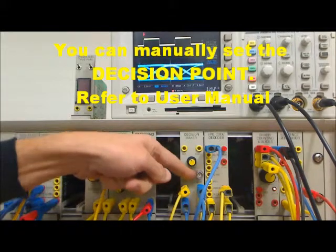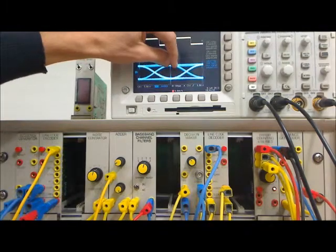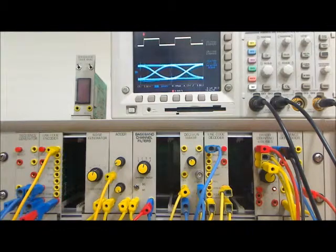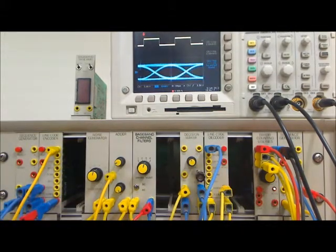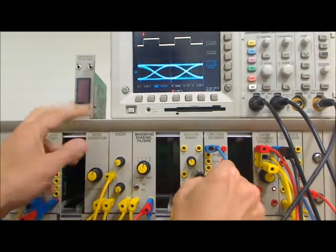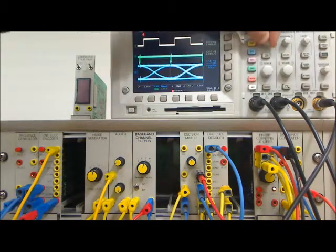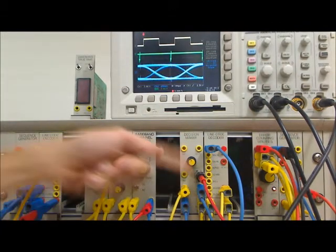There's a signal that comes out of this B and C connector. If you connect this signal to your Z modulation on your scope, you'll have a highlighted point on the eye. Another option is to view the signal simply on another channel of the scope, if you happen to have multiple channels. In this case, I'll take channel 4 of the scope and have a look at the signal.